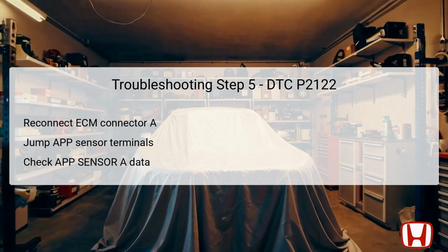A voltage reading of 0.2 volts or less at this stage indicates a problem with the ECM, perhaps requiring a software update or substitution with a known good ECM to rectify the issue. If the voltage is above this threshold, it is advisable to replace the APP sensor. Each of these steps is integral to properly diagnosing and correcting the P2122 error.